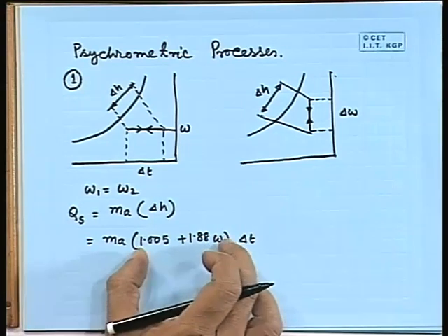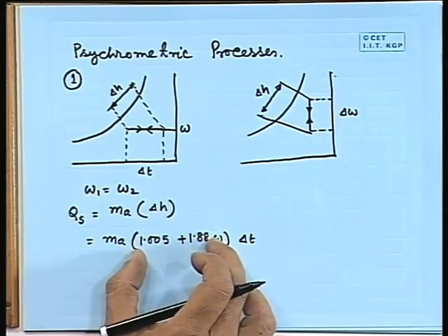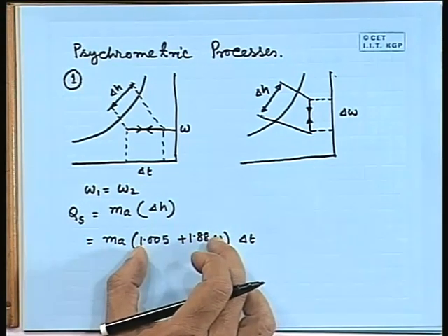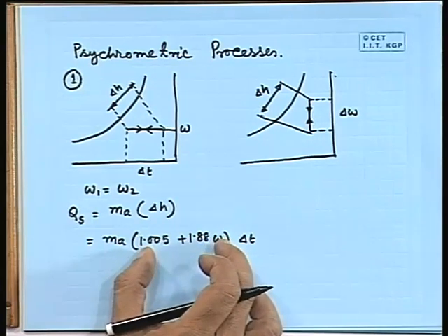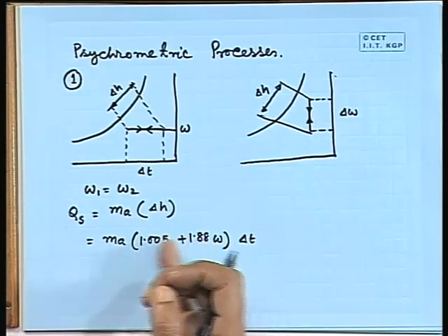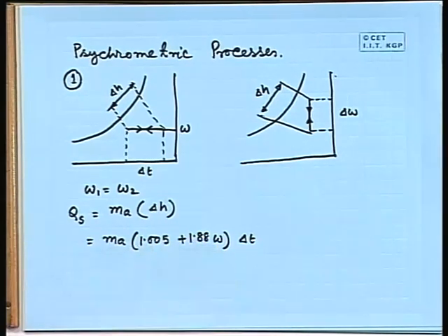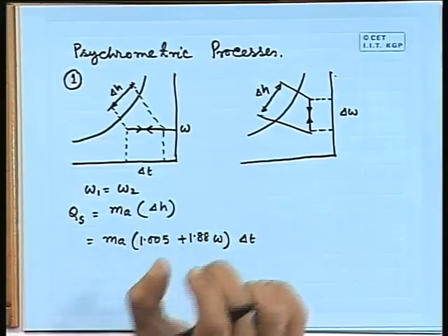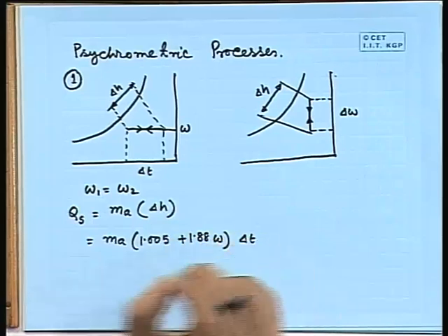And then again one can take an approximate specific heat for the moist air which I have introduced, 1.02016 into delta T. That means I am eliminating W. Please try to follow that.